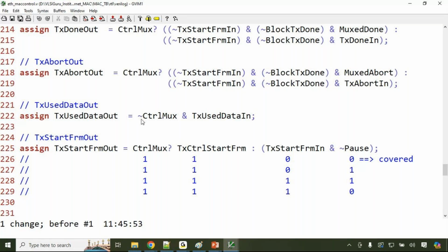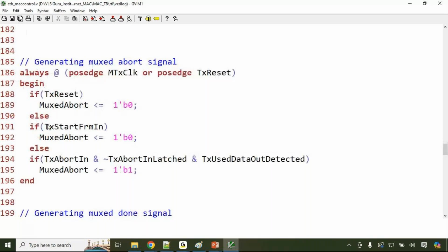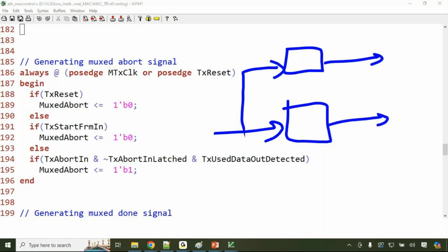So the role of a functional verification engineer is to detect this kind of bugs. There are two ways I will suggest. One is he opens each file, goes through each line and tells this is good, this is bad, this is good. That is one approach. Second is he follows a process where he takes a design and has a reference model, his own model, where he applies the same inputs. He gets the actual output from the design and compares both of them. If the output matches, it is good. If the output doesn't match, there is some fault in the design.